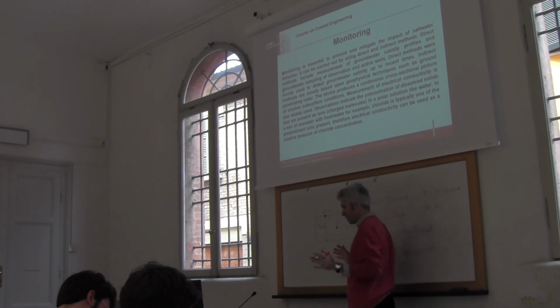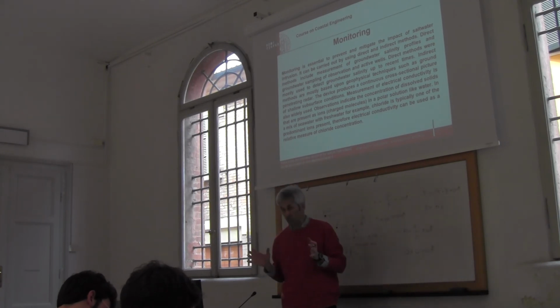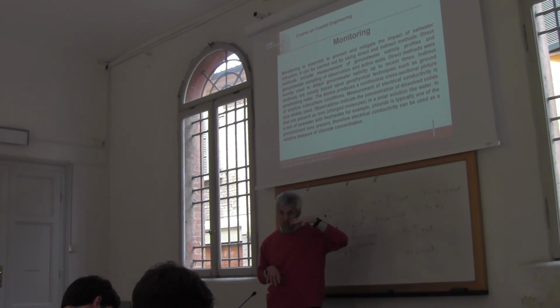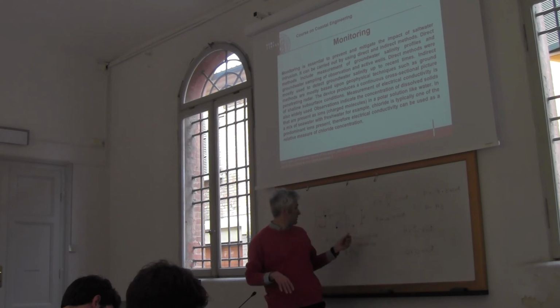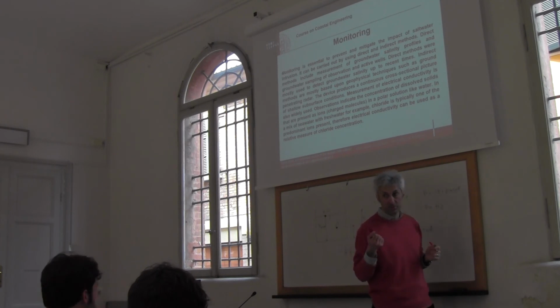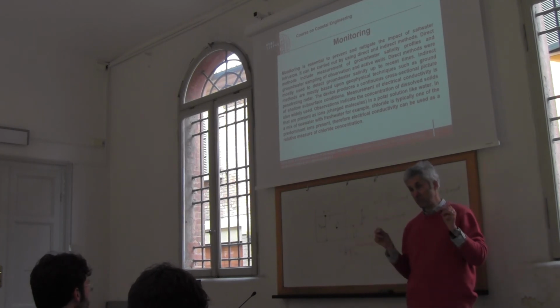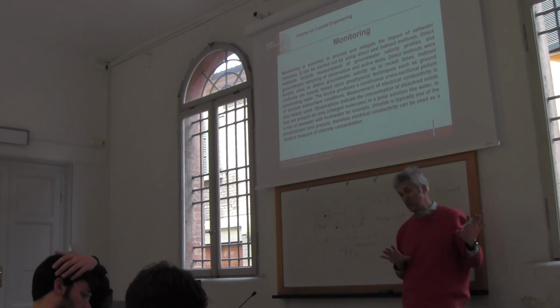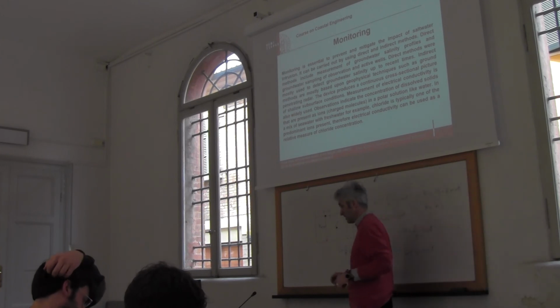Monitoring is extremely important because we need to be aware of the situation. We need to prevent, we need to understand in advance if the salt wedge is expanding. In the piezometer we can also measure the salinity. We take a sample of water from the piezometer and we measure the salinity because it allows us to understand if the salt wedge expanded.